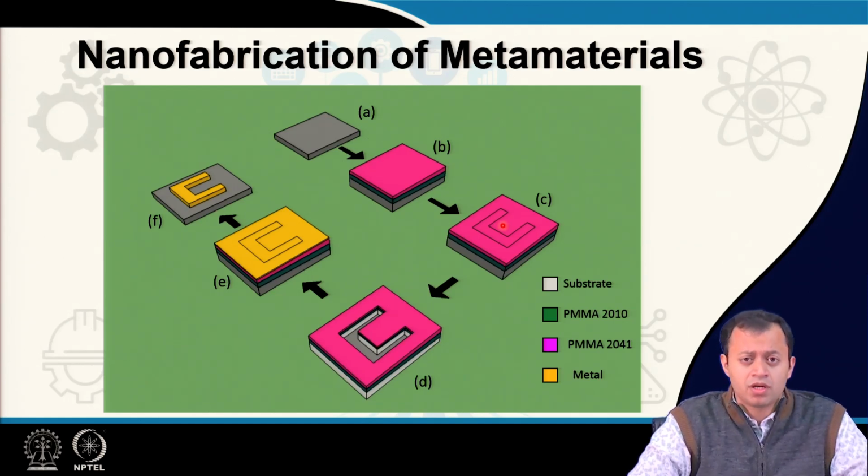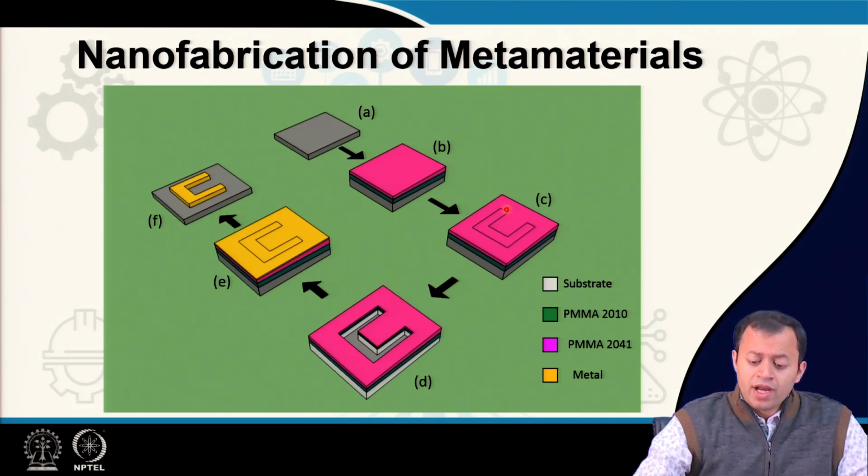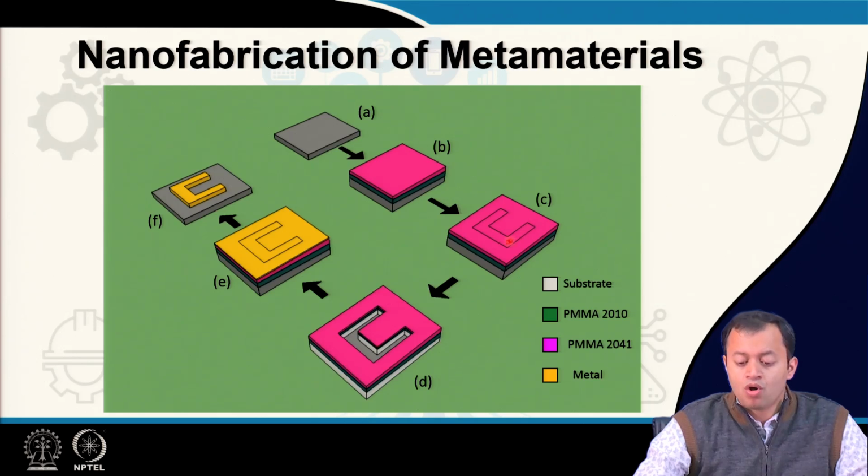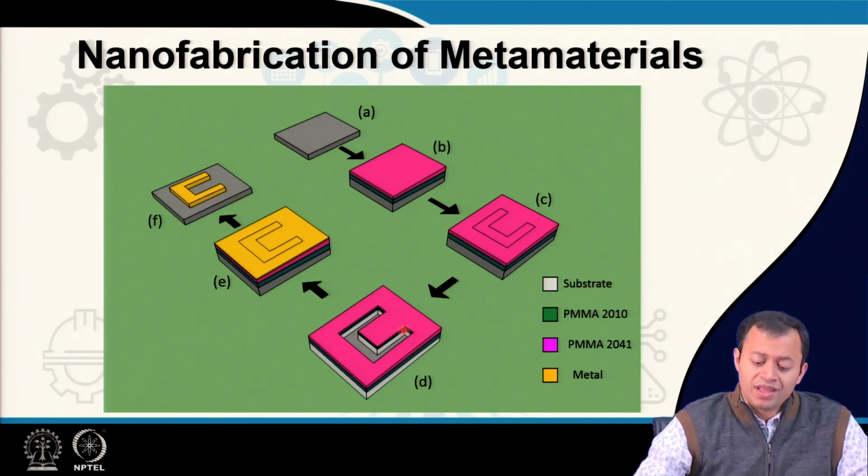How small is 10 nanometer compared to the width of your hair again? Remember, I gave you the formula. Whenever the electron falls on top of that PMMA, polymethyl methacrylate substrate, the bonds break and this part becomes weakened. When this part becomes weakened, we can simply dissolve it by putting it in some kind of solvent. That solvent puts a trench into the system, dissolving the polymer, the PMMA, not the substrate.